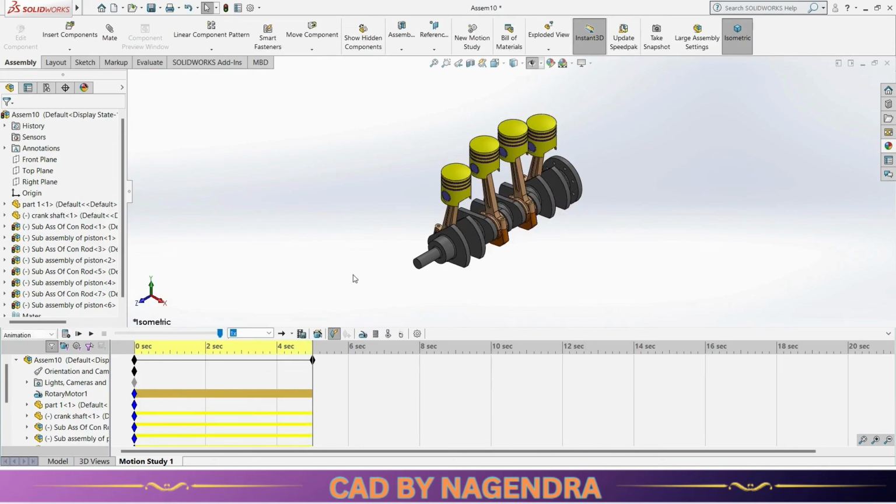Then next to that, we can increase or decrease the speed of that motion simulation. For example, I'll keep it here at 0.25, like slow. Then we are able to change different orientations here. Normal means only in one direction, from starting to ending it will come. If you make it loop mode, the same step will be repeated again and again. Reciprocate means first it will go clockwise, next it will come in anti-clockwise direction. Now for this one, we will make it loop mode.